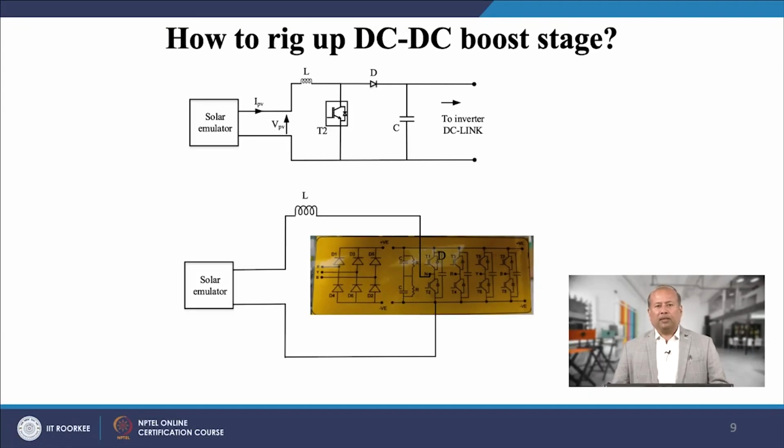For our application, we are using only 3 legs because we are demonstrating solar generation for a balanced 3-phase 3-wire system. Moreover, we are talking about only the single stage conversion. It is also possible to use the same setup for 2-stage conversion as well. The leftover 4th leg can be used to build the DC-DC boost stage. And how can we do that? Let us understand in detail.